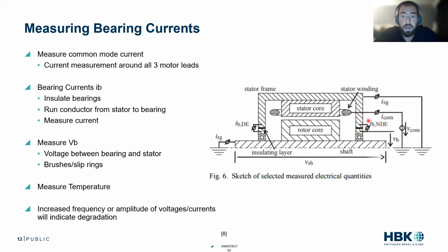You can measure your bearing currents, which is this IB here, but you need to insulate your bearings. Difficult, it's a pain, I know. Run a conductor from the stator to the bearing, and you can physically measure those currents. It's a pain, but you can do it.